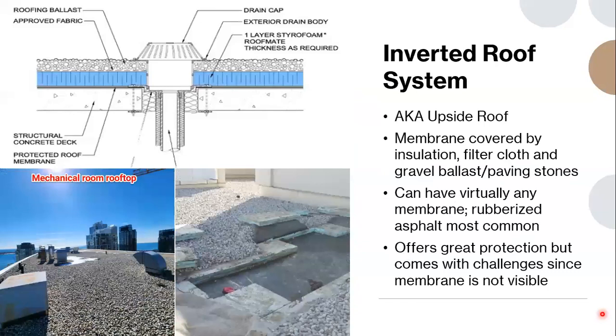Sorry, Kelly, I just want to say for that, the hot rubber roof is a good example of cracking under the UV rays. That's why it's really important to make sure that none of your roof system is left exposed. That system, if left open to the UV rays, would crack.